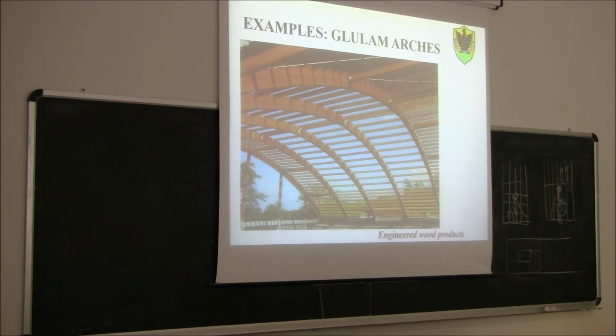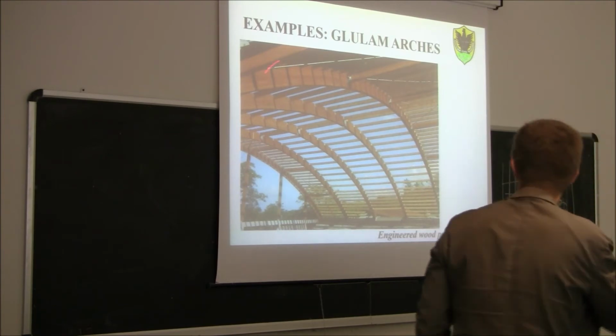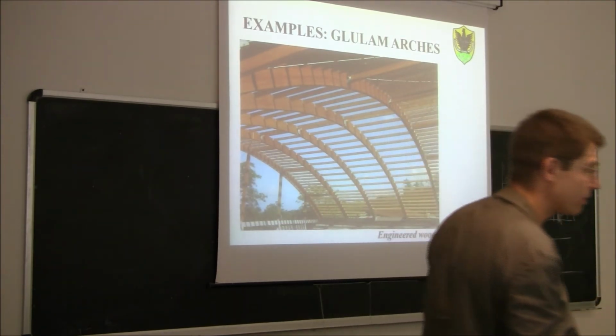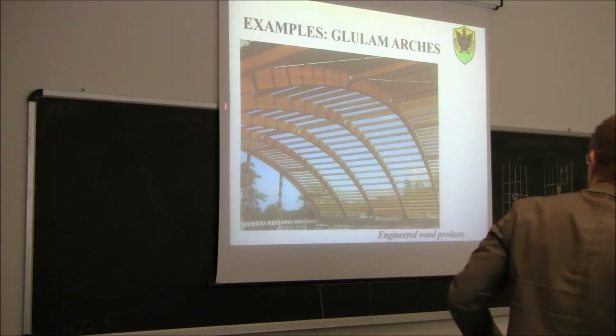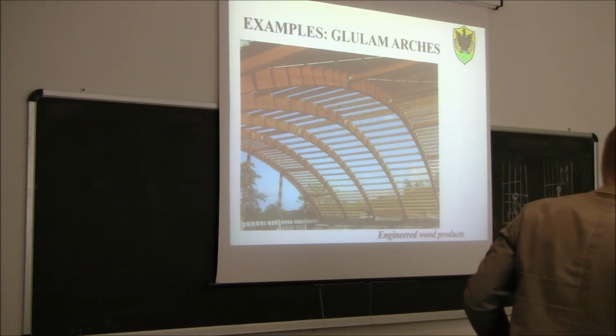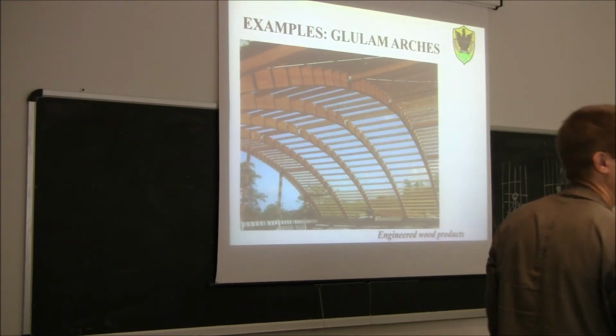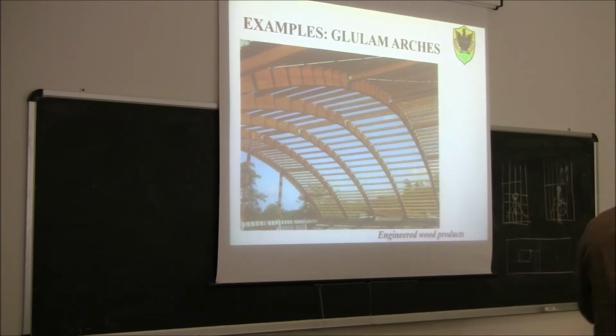Okay? While instead the wind forces and earthquake forces in plane, so parallel to the 3-pin arch, will be resisted by what? What is the structural system resisting wind and earthquake in the direction of the plane of the arch? The arch itself. The arch itself. Okay, the arch itself is a 3-pin arch, so it's a statically determinate system. It can carry the horizontal loads also, not only the vertical loads. Okay? Is it clear?